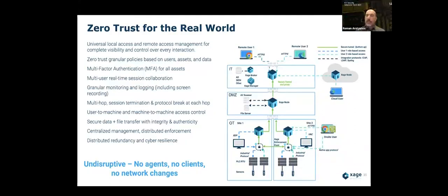Okay. So continue on with the questions here. We've got a few more queued up. Only got a few minutes left. So you mentioned in the presentation, let me just take a look here at the question. There was machine-to-machine communication that was mentioned. How does ZTNA's solution know if that is expected engineering or ICS traffic, or if it's an adversary conducting internal ICS lateral movement? Yeah. So the policies are built up front, right?